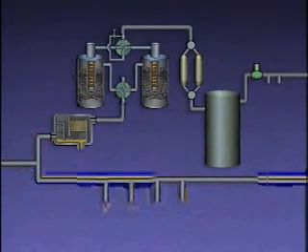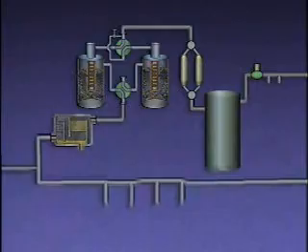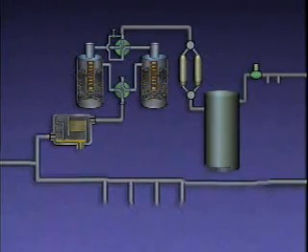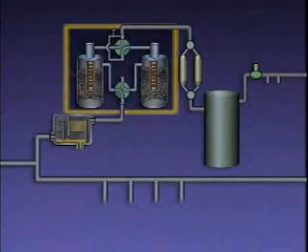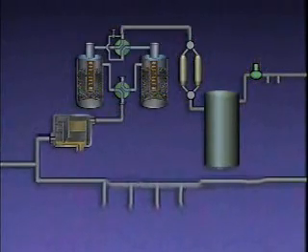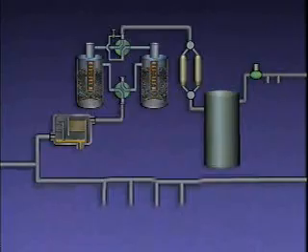But pneumatic instruments require compressed air that is extremely clean and dry, and at a lower pressure than the air supplied by the plant air header. Providing this quality of air requires devices such as an oil separator, a desiccant dryer, filters, and a pressure-reducing valve. A small amount of oil is frequently present in the air discharged from a compressor.